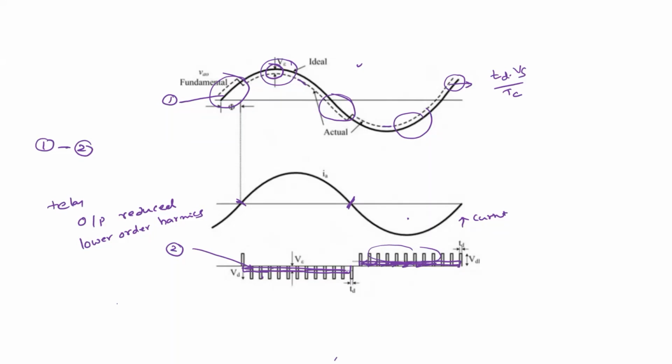How to compensate is based on the polarity of the current, because this error is varying. Based on the polarity of the current, this voltage gain or loss is varying. Therefore we need to identify the current polarity by using a current sensor, and we need to add whatever this error is.